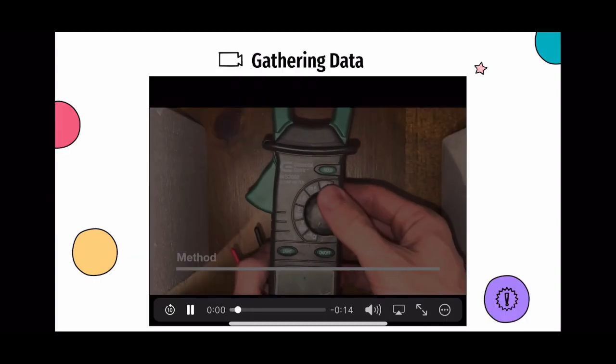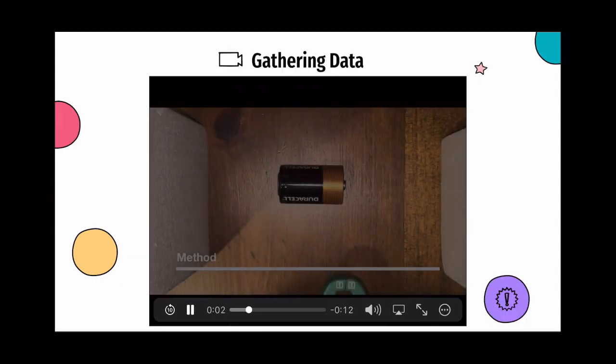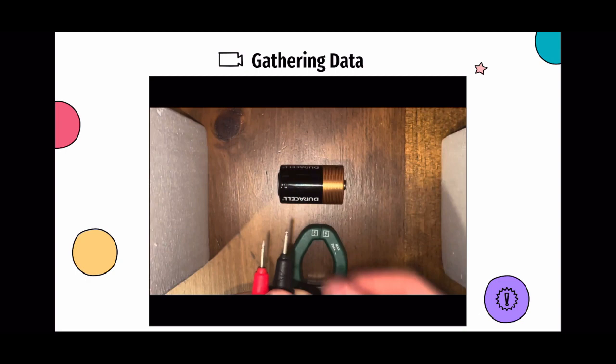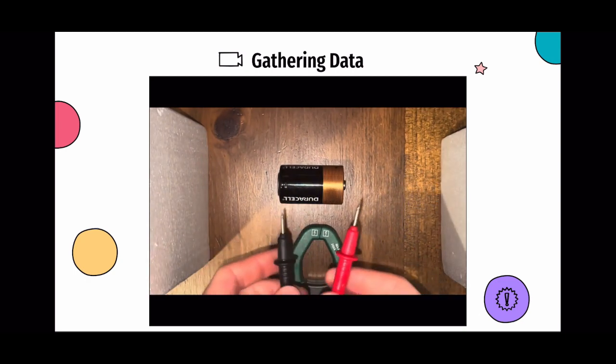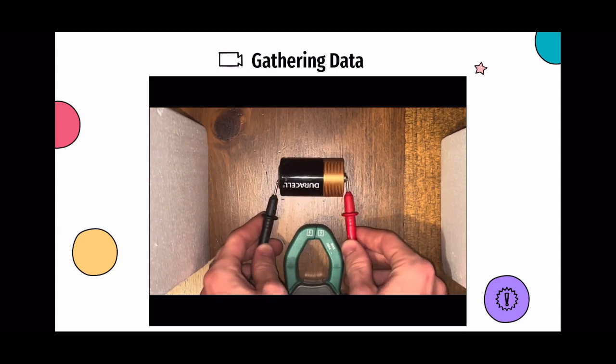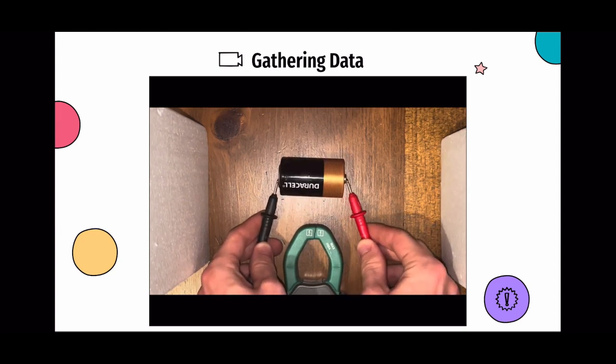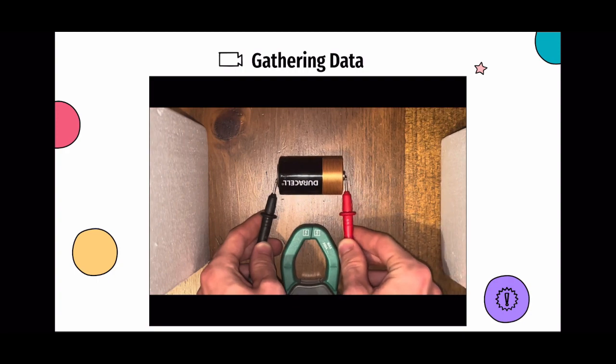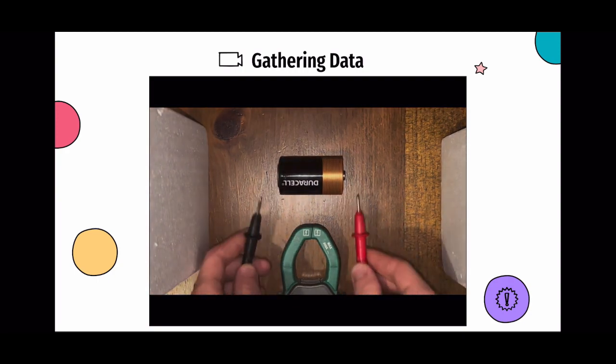batteries. Here's the procedure. Read the voltage of the randomly selected batteries one by one using a commercial clamp meter with a readability of at least 1/10 of a volt with an uncertainty of 3/100 of a volt. Set the meter to read volts and direct current and remove probe covers. Connect the red positive probe to the positive end of the battery and the black negative to the negative. Make solid contact to increase the surface area in contact and remain still for a second to get an accurate reading. Get the next battery without replacement.